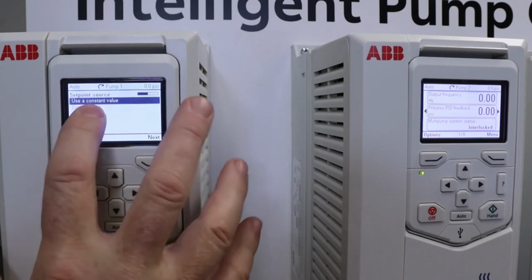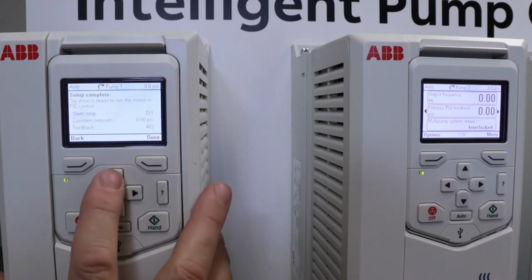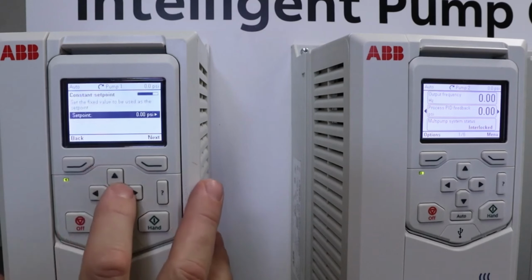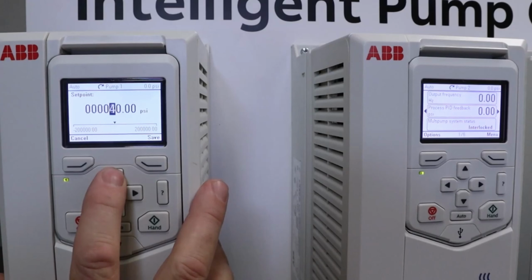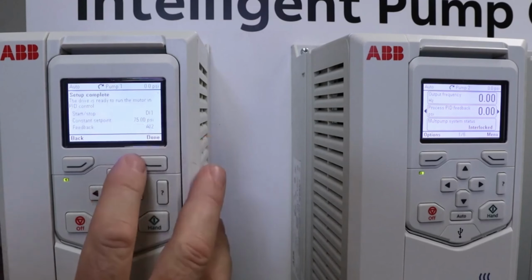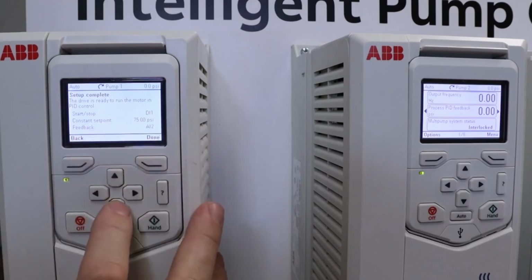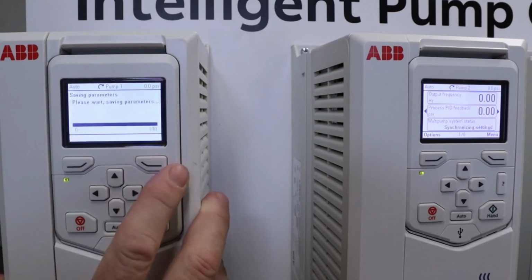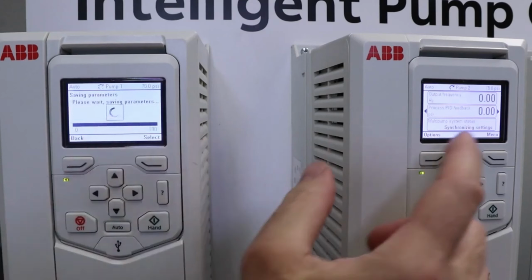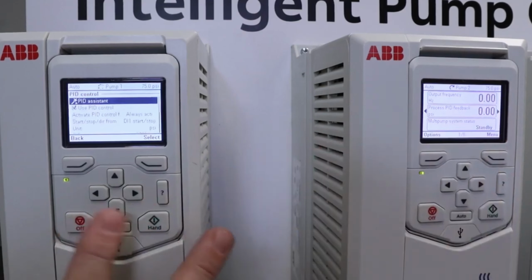We're going to use a constant value as the value that we need to look for, and that's going to be a set point. I have to back up, set point is going to be 75. Save. Next. So DI1, 75 PSI, pounds per square inch, is our set point. Feedback is AI2, analog input 2. Done. Now it's saving parameters, and if you see what happened over here, 75 PSI showed up there as our set point. Okay. So now we have that data in place,